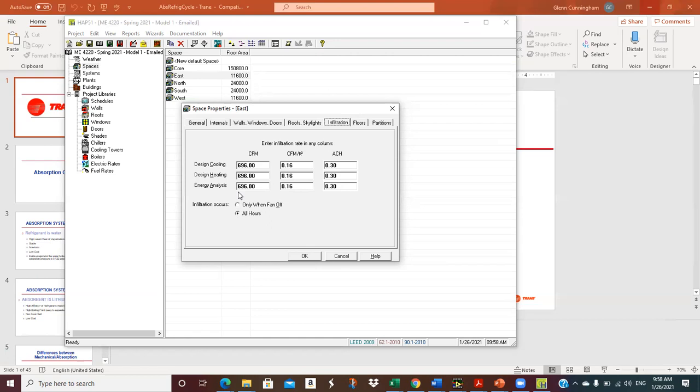And then you have to make some assumptions anyway. I did that once or twice and spent 2 hours doing calculations and then had to make a bunch of assumptions. I said, well, why don't I just assume half an air change and I'm done? Because I'm making assumptions one way or the other. Now maybe the crack method might be a little better, but I'm way too lazy to do that. But anyway, there are some other techniques for estimating.